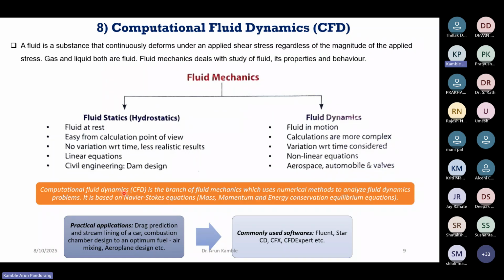So computational fluid dynamics, this CFD, is a branch of fluid mechanics which uses numerical methods to analyze fluid dynamics problems. Generally it is based on the Navier-Stokes equations, which are related to the mass, momentum, and energy conservation equilibrium equations. So these are some of the practical applications: drag prediction and streamlining of the car, combustion chamber design for optimum fuel air mixing, or in the case of aeroplane design, we can also use this CFD analysis. These are some of the softwares: Fluent, Star CD, CFX, and CFD expert.